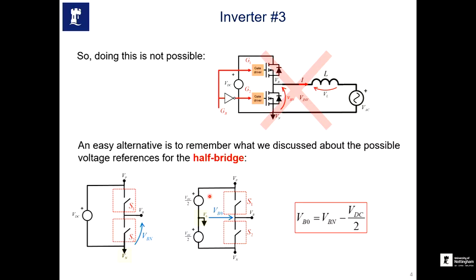we just do a very simple change, which is basically splitting the DC link and putting a ground or reference in the midpoint. And we saw in earlier lectures, these two circuits are equivalent. All we are doing in here, instead of taking the reference at this point, the negative DC link, we are taking the reference point as the mid of the DC link. So if we look at the voltage between this point and this point, if you say this is our output voltage, VBO, then basically we can write the equation